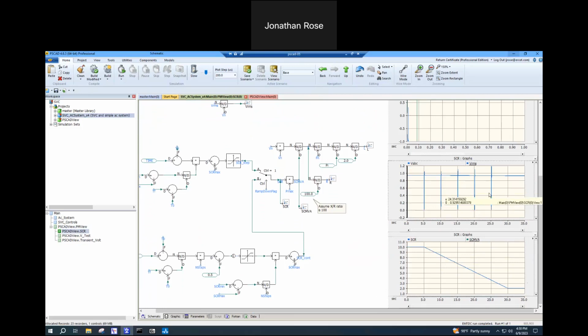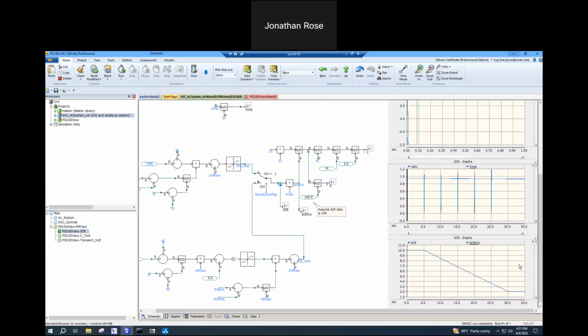And we apply faults during the short circuit ratio test to disturb the operating point of the machine to ensure it's actually stable for that weaker and weaker grid condition. So the idea is, as the system gets weaker, you might find a breaking point where the model will eventually go unstable, especially if you continue it on and test it down to 1.5 or 1.2 short circuit ratio.